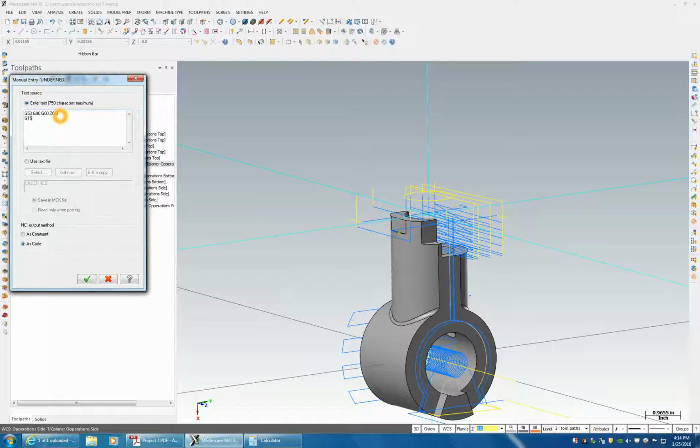Now I'm going to do G154 P1. That's a work offset, above G159. X of 0, Y of 0. So whenever you're setting up the machine, you're going to bring the table to where you want it at the door, and you're going to set that as the G154 P1 offset. M00, flip part.